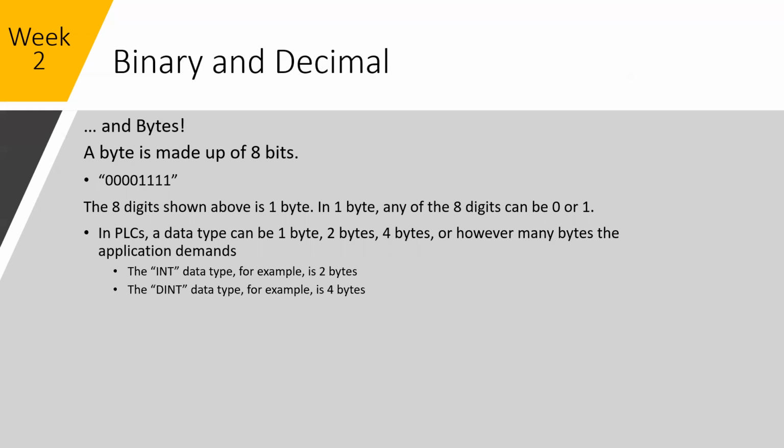I think, was it Scott, you were saying you used the PLC 500s and the MicroLogix? Yeah, that's right. So some of the older controllers will actually only use a 2-byte system, or an integer data type. That's going to be a limitation of the processor inside of that particular PLC. When we get into the ControlLogix, CompactLogix, I think Siemens will use double integers just because they have more powerful processors. They can use the larger data types.